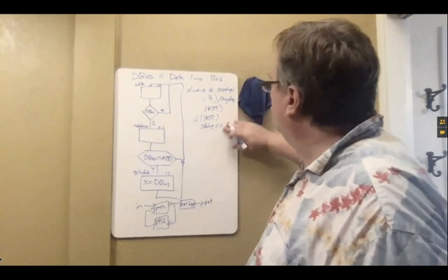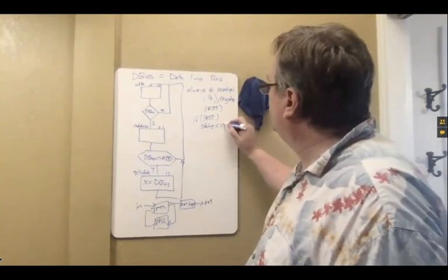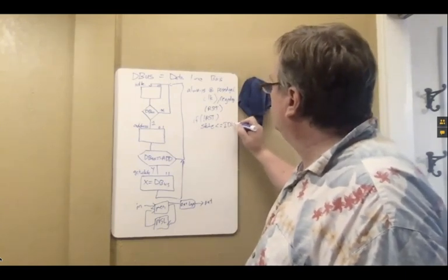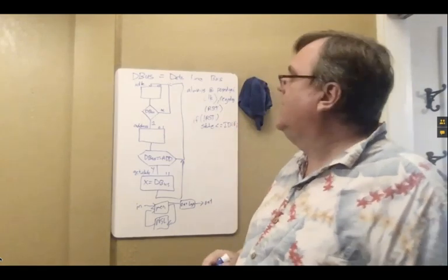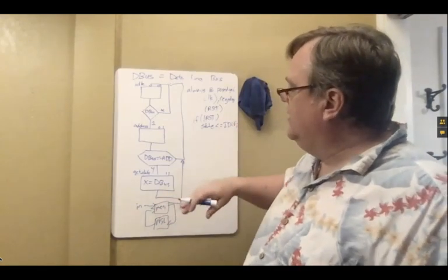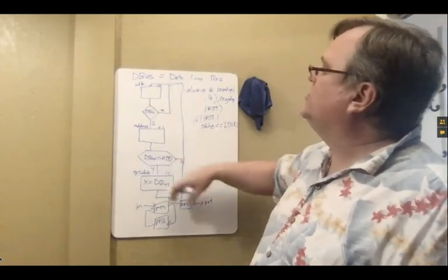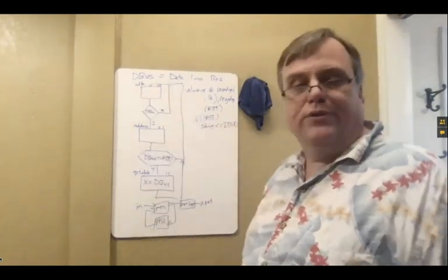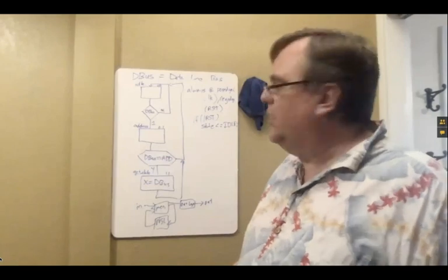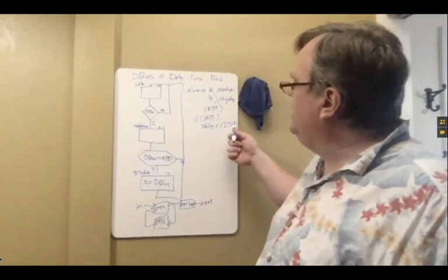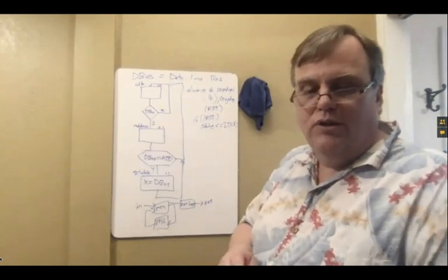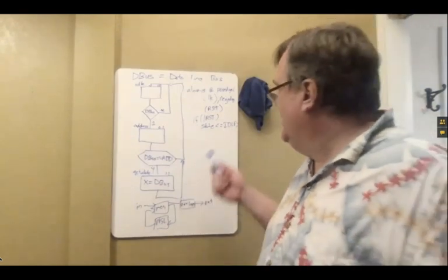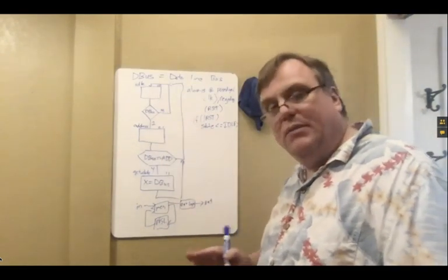Now the best way to do this is instead of 0, I'm going to say I want the state to go to idle. That way, if somebody does a reset, I want to go back to idle and wait for the next start-up. That way, if somebody renumbers idle to start some other place than 0, they can. 0 is, in my opinion, the best spot to start.